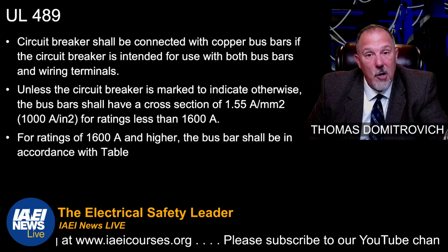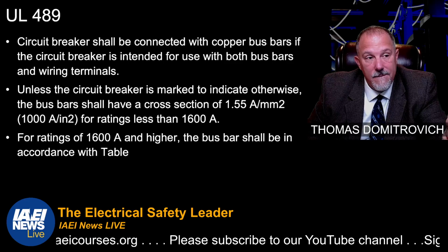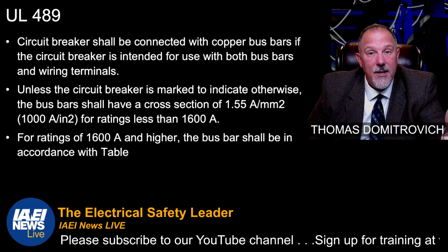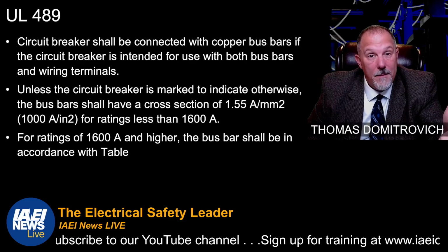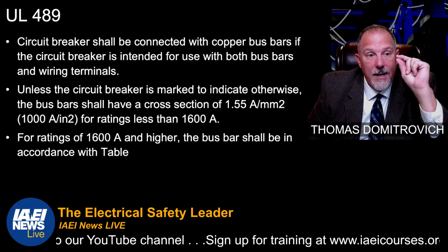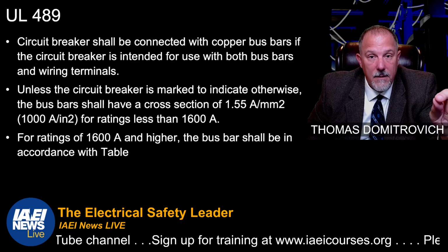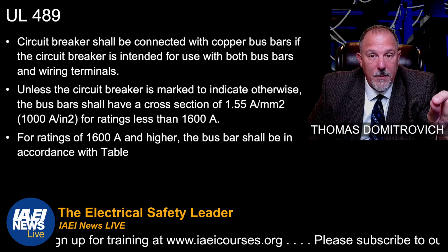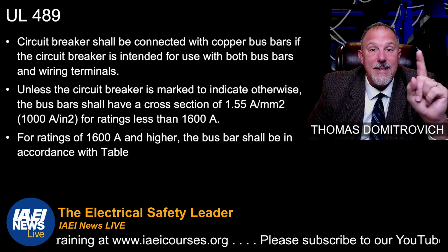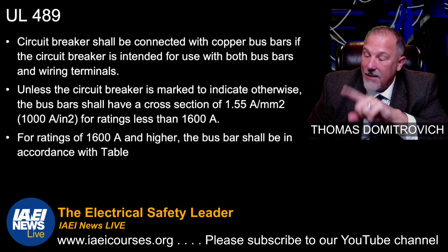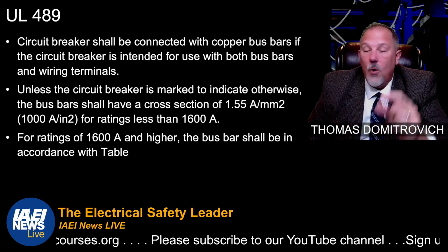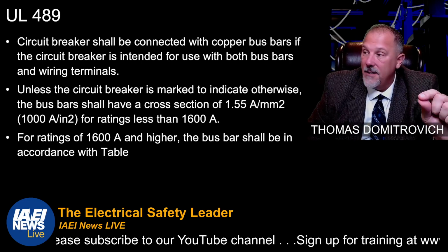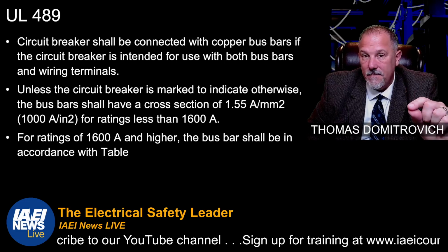The size of the enclosure makes a difference. The construction of the bus that you're going to be terminating that breaker onto makes a difference. I think it's safe to say it's not just about changing out a circuit breaker. You need to look at the assembly, and that's why in 210.20 it says, where the assembly, including the overcurrent devices.